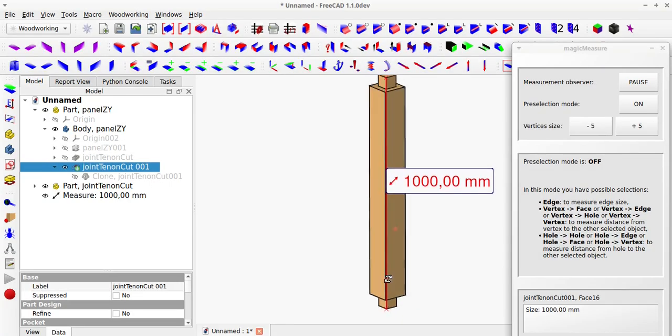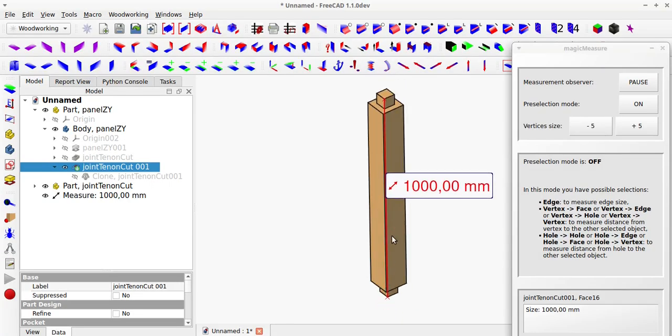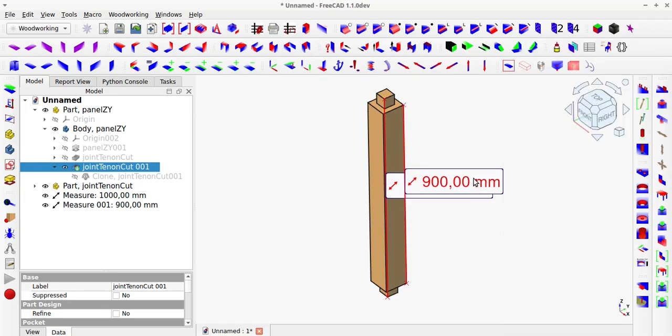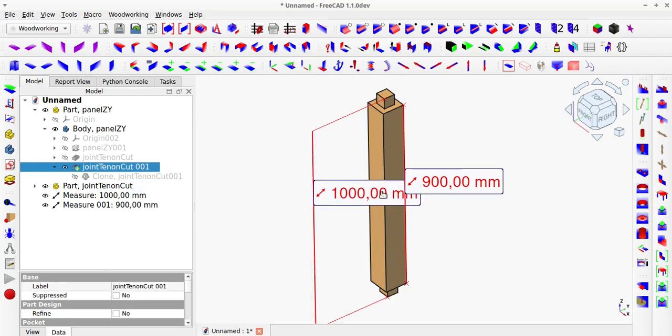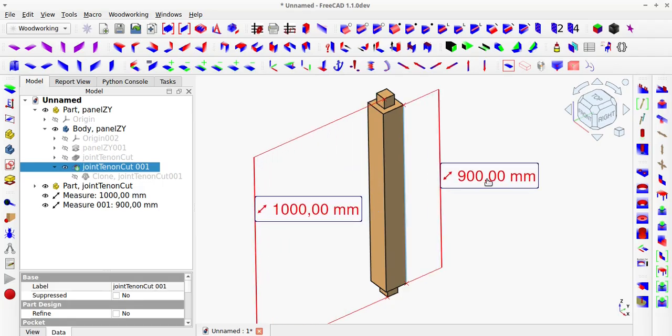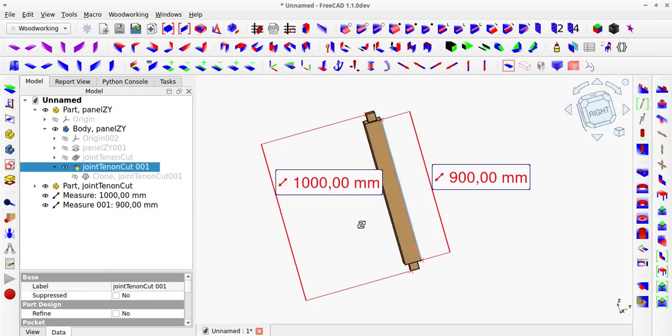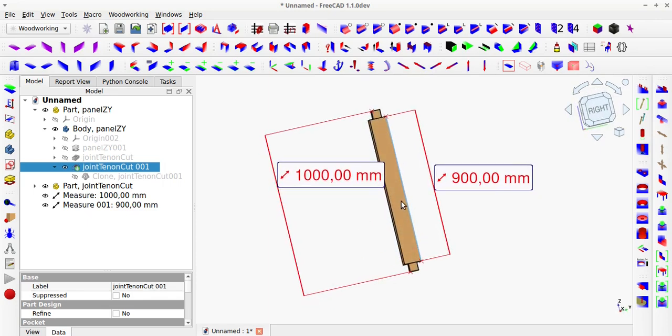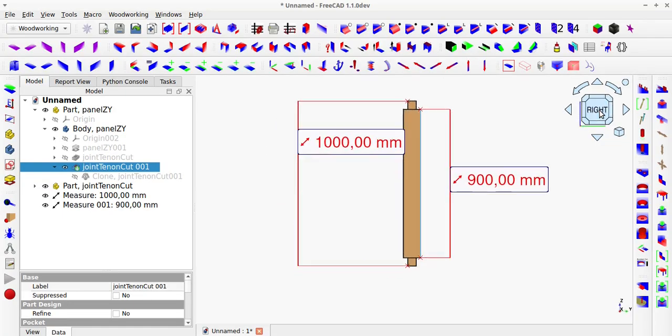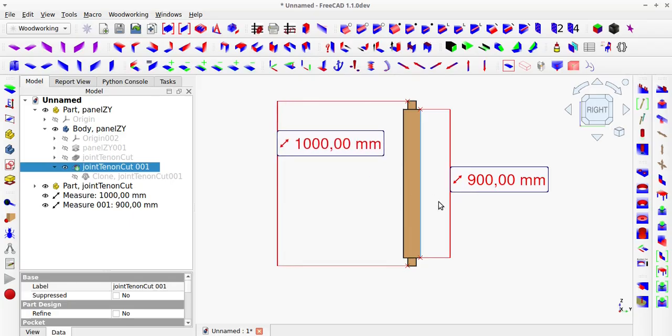However, as you can see in this case, the tenon is part of the element and changes the dimensions of the entire element. The created tenon has the same dimensions as with the tenon as a dowel, but in this case it is not hidden inside the element but merely cut from the element. Unfortunately, this must be kept in mind when designing the main structure, with the overlap to take into account the tenon that will be cut later, or cutting such tenons at once.